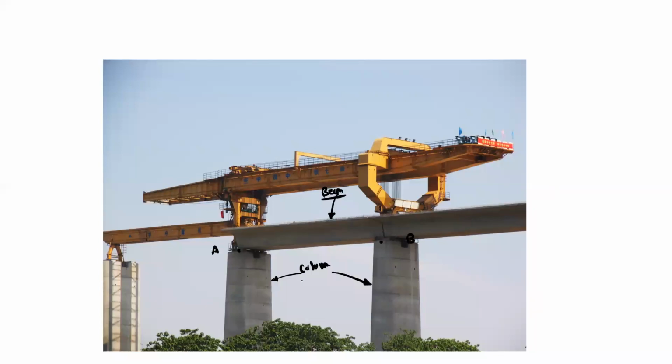These columns will provide the necessary support reaction so that they can support the complete beam or the weight of the beam. If you draw the free body diagram for this complete beam, you will show the reaction Ra here and the reaction Rb here. Suppose some vehicle is passing over this bridge, then it will provide the load. We can consider this as W1 and this as W2. Here we are not considering the weight of the beam, but the beam will have its self weight, so we have to consider that self weight when we analyze this complete system. This is the real life application for the simply supported beam.